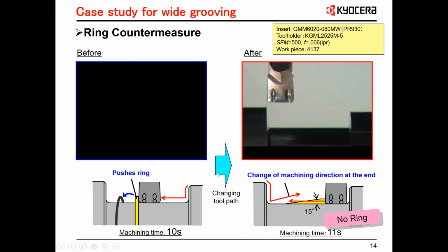Now we're going to come over and do the long wall, but when we do this plunge, we're going to walk over just a little bit at an angle. We're going to bring the tool up at an angle, 15 degrees or so. Then we're going to come over, finish the short wall, and come across. Basically, when we get to the end of this slope here, there's nothing left to push away. So I'm going to let you watch this now.